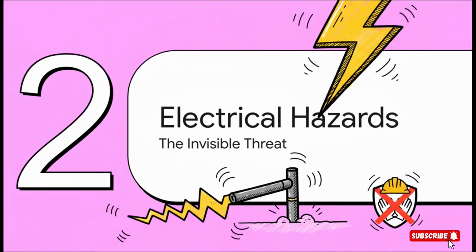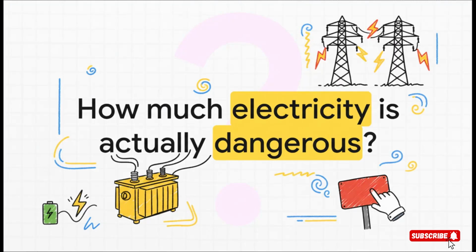All right, now let's talk about one of the most pervasive and honestly one of the most misunderstood risks in cathodic protection: electrical hazards. Getting complacent in this area is just not an option. It can be fatal. A lot of CP systems run on very low voltages, and that can give you a false sense of security. But dangerous AC voltages are often right there, especially when you're working near power lines or directly on rectifiers. We have to respect all levels of electricity.